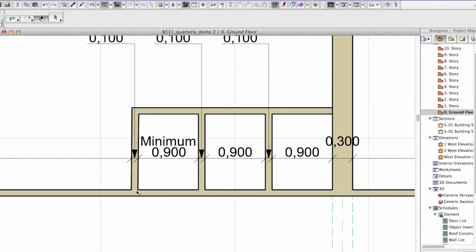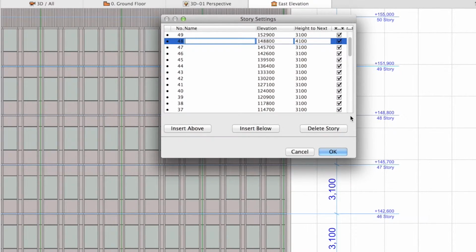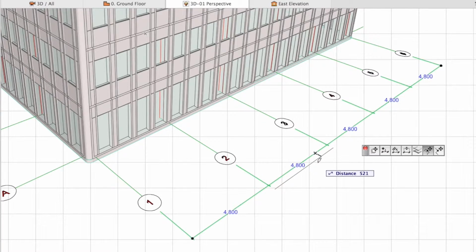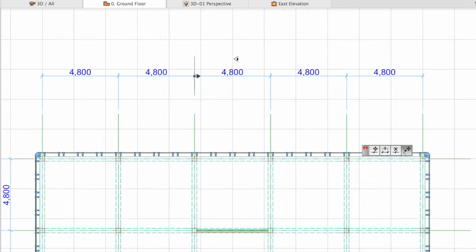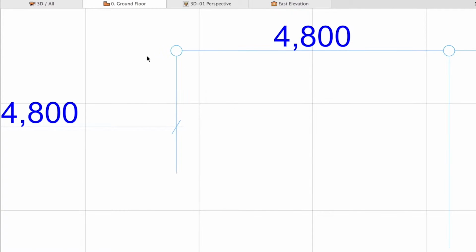Archicad now handles fully automated multi-line dimensions. Associative dimensioning of story-level lines on sections and elevations means one-step completion and updates of story-level dimensions. Witness lines with no overhang can also be used to help match specific strictly regulated country and office standards.